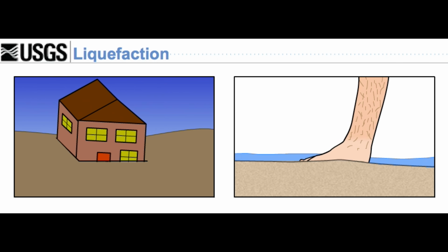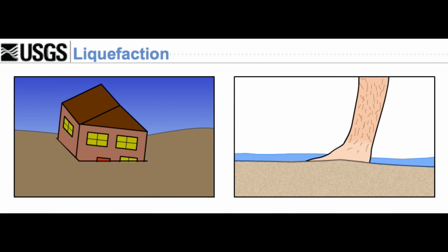Liquefaction is when a sandy material that typically would work just fine in everyday life, if there's an earthquake, that can tend to liquefy, and it won't support the bridge. And so it's just critical because you were counting on something to hold the bridge, and it's not.